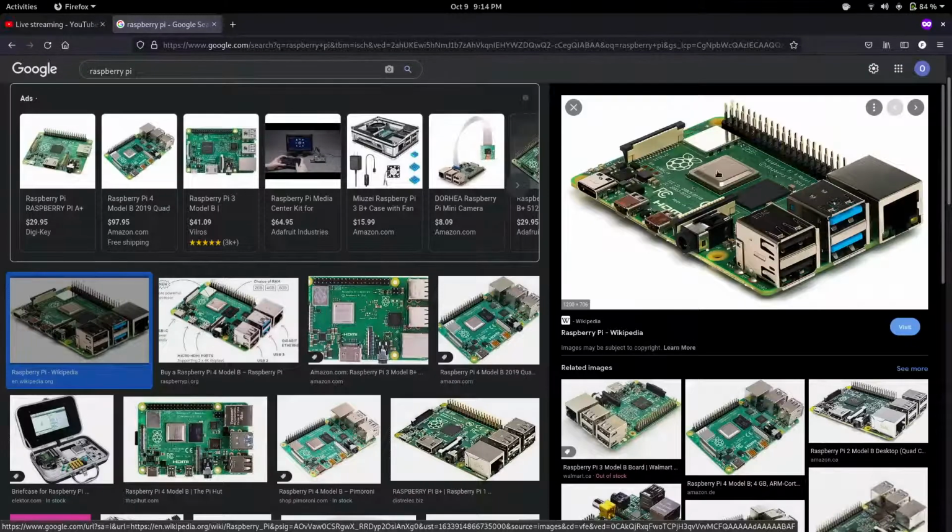Specifically, I think it's BGA, which means ball grid array, which basically means there's a whole bunch of contacts on the bottom of it and little balls of solder on each one, and they put it on there and heat it up and it melts it on. So if you look at the back of the Raspberry Pi, you will see that there are not pins coming out of the CPU going all the way through the board. It just sits on top of the board.